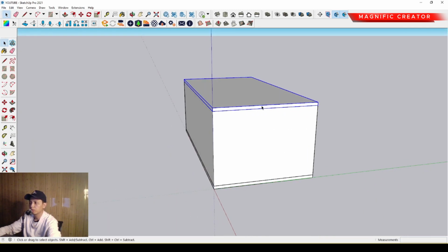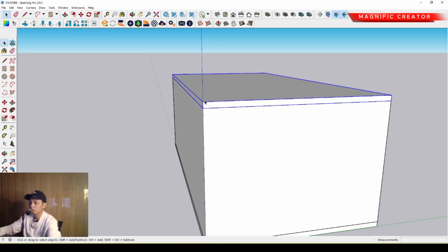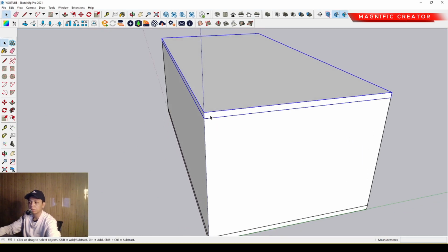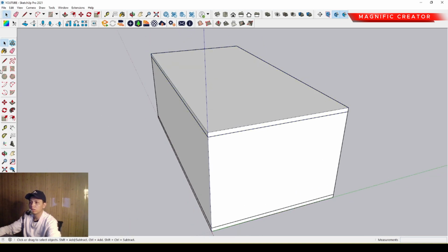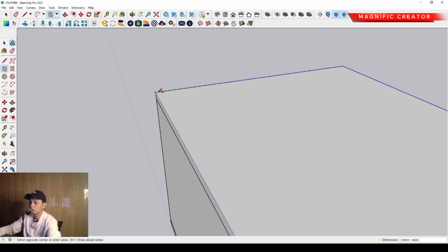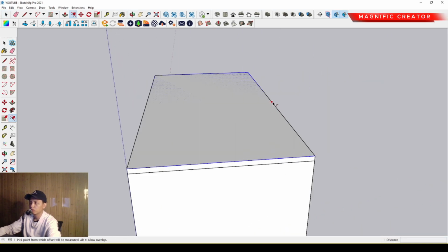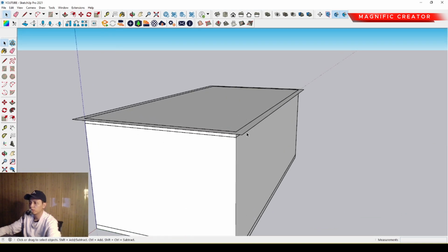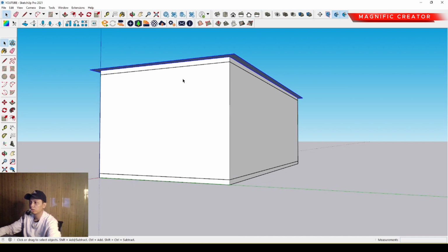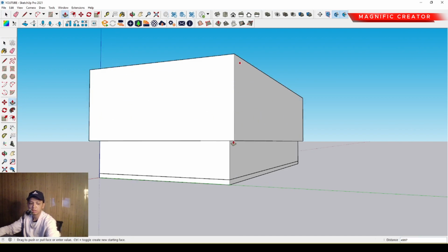Okay, and then we can make the secondary skin anyway. We can use a rectangle, then place it from corner to corner. Then we can offset it outside around 500 millimeter. Then we can erase some unnecessary plane and line over there, and push it down until the proportional shape as we want.